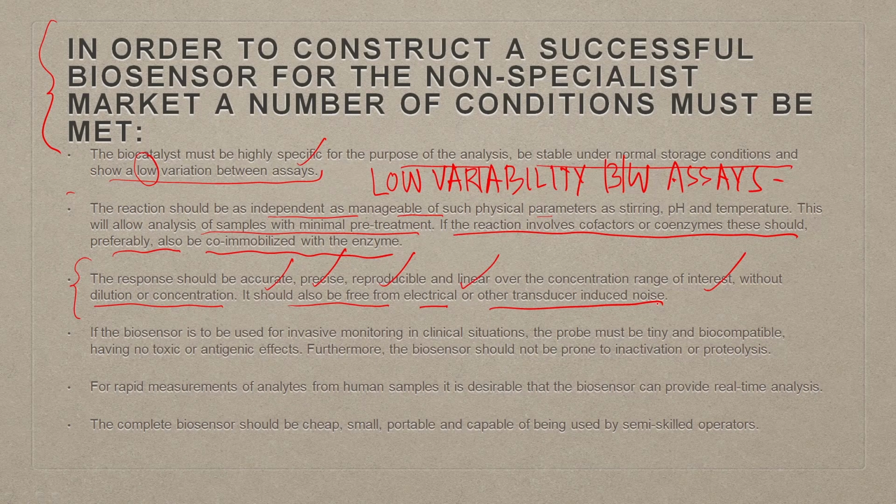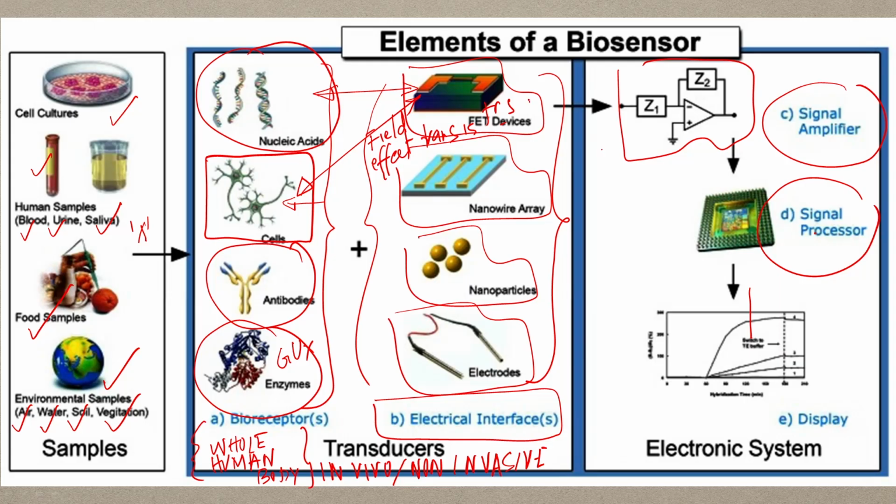So, when we are doing these kind of measurements, one has to understand most of these devices come with their own set of noises. If the noise of these devices is more, then it will interfere with the biological signals, and noise cancellation or having devices with minimal noise is highly preferable for success of these kind of devices.